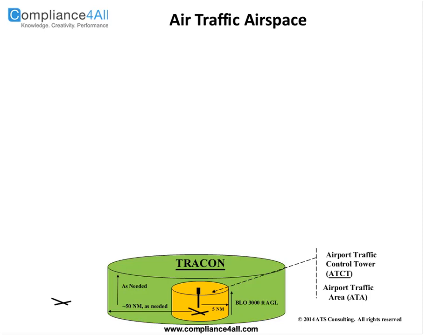And its airspace allocation is usually 50 miles, which was the range of the radar, the airport surveillance radar, about 50 miles. And the airspace above it was usually, back in the day, about 7,000 feet, but since the strike, now it goes up to whatever it needs, and some are as high as 23. So these are all variable, and one thing about the FAA or the Air Traffic Control System that I really admire is its flexibility to adapt to what needs to be done and what it has to work with. So in this case, the 50 miles is kind of the limit because of the radar range, unless you consolidate TRACONs into a single building, and then you have multiple radars. And the altitude is what is necessary.